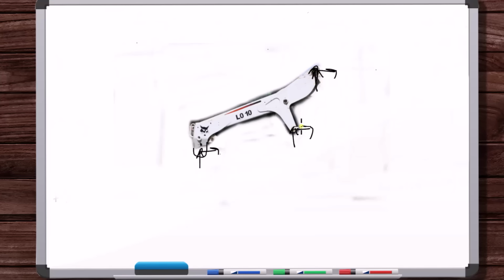Looks like these are pin connections. There's no rotation being constrained. We'll say this is planar. We're not worrying about forces into or out of the page or moments in those directions. But, okay, there's a pin here though, right? So I think it always made sense to me that, yeah, if we could make a cut, cut a plane here. But now that we don't have a cut here, we're not going to put all these reaction forces inside the material, right?